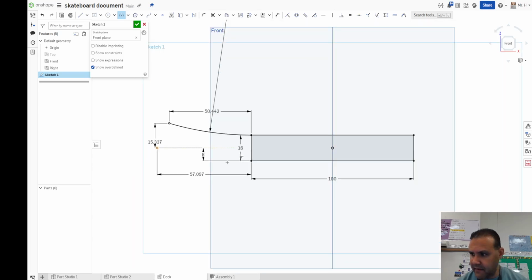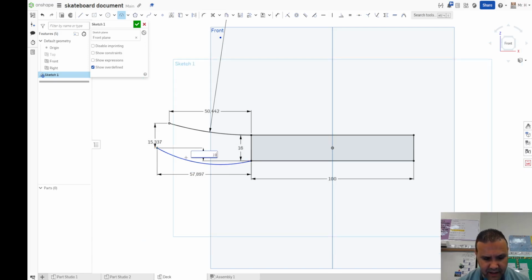And then if I do another 3-point arc from here to here, and I put this 193.062 like that, kind of gives me the same design. Honestly, it's a preference. This is a lot easier to do sometimes for most people, but again, it really won't matter in the end. So I'm going to come in here and just use my line tool, put a nice horizontal line there, connecting them through, and I'm done.